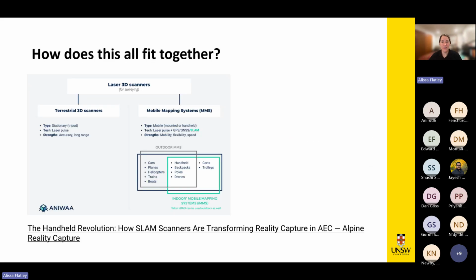So how does this all fit together? Well, terrestrial scanners, the static ones are very useful, but there are some downfalls. So these surveys are associated with labor-intensive equipment setup. This can require multiple field days for surveys, which you typically would have overlapping scan data. And for that, terrestrial laser scanners have a much smaller areal coverage compared to UAV-derived scans.